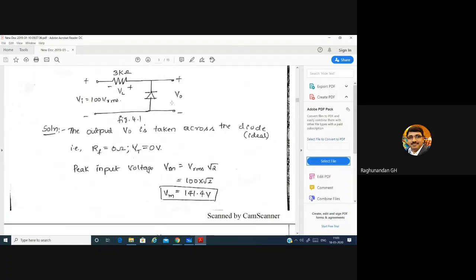See how we got this Vm by pi: whenever a circuit has a single diode, like this one circuit with one diode, it is compared with a half wave rectifier. The formulas we derived for the half wave rectifier, the same formulas we'll use here to find the peak voltage VM and VDC, that is the average DC voltage.